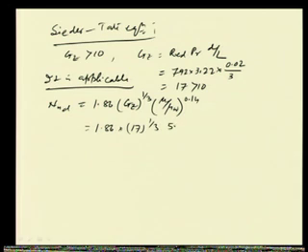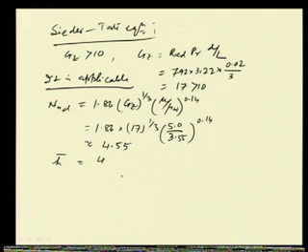It is 5.0 by 3.55 whole to the power 0.14. So, this is approximately equal to 4.55, and then from there we can find out what is h bar, or average heat transfer coefficient. This comes about, it is 4.55 into d by k, and this is becoming now 147.9. So, we have got a value of heat transfer coefficient.